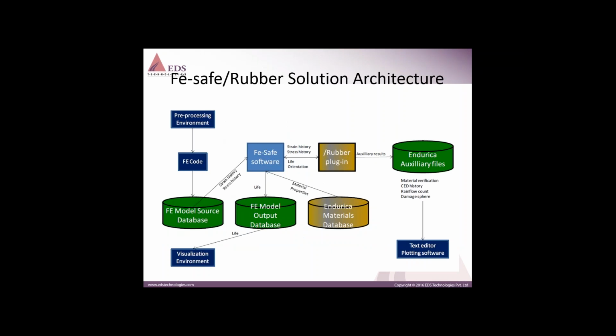And you use your FEA solver to define the typical scenario of loading over time. It can be a simple sine wave, or you can also use complicated road load data.